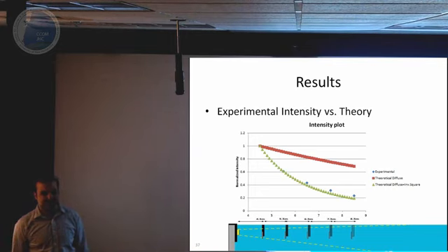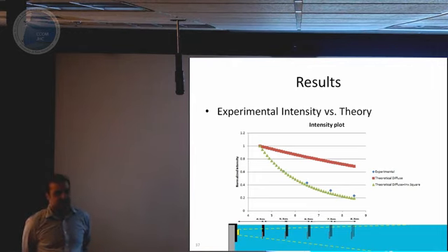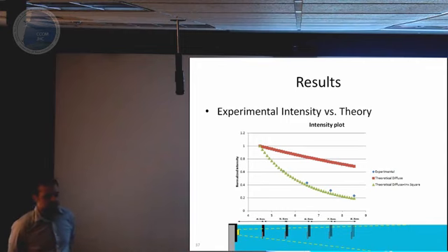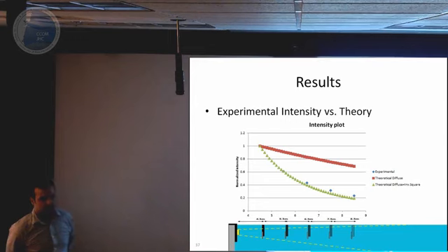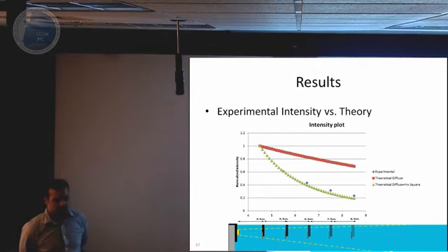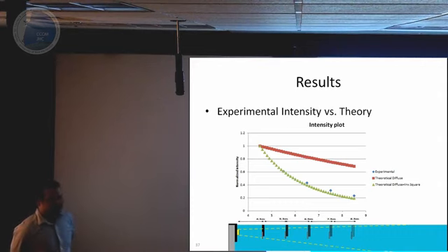Like most students. So one more question: when you did the estimation part of the problem, calculating the distance between the leader and the follower, it looked like you were always solving that in 2D or maybe even 1D. That's inherently maybe a 6D problem. You've got a delta X, delta Y, delta Z, and then maybe 3 Euler angles describing the relative orientation of the two vehicles. Have you thought about expanding that to solve for all of those parameters at once?